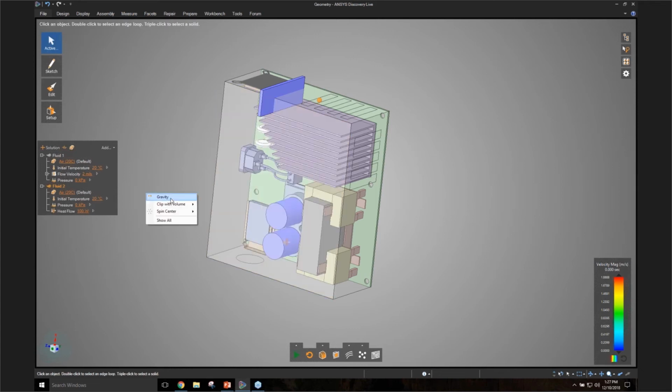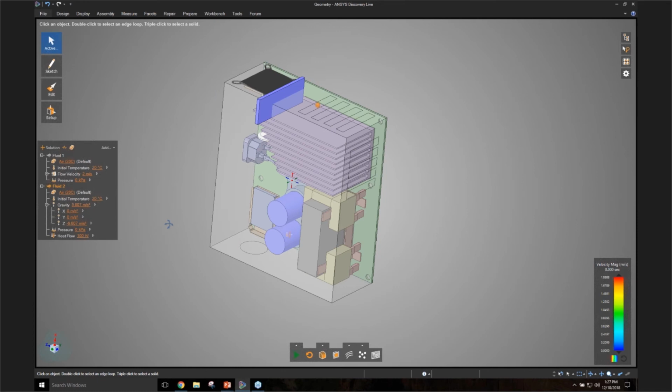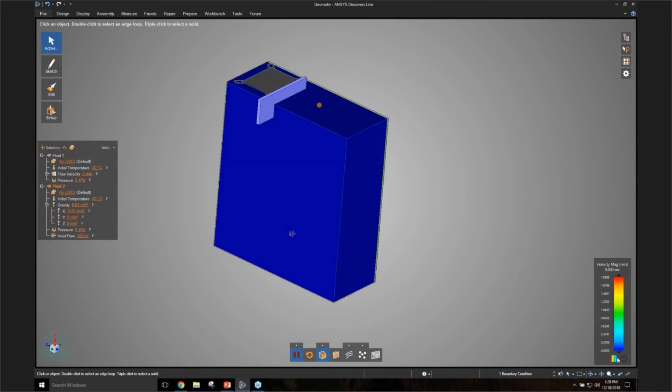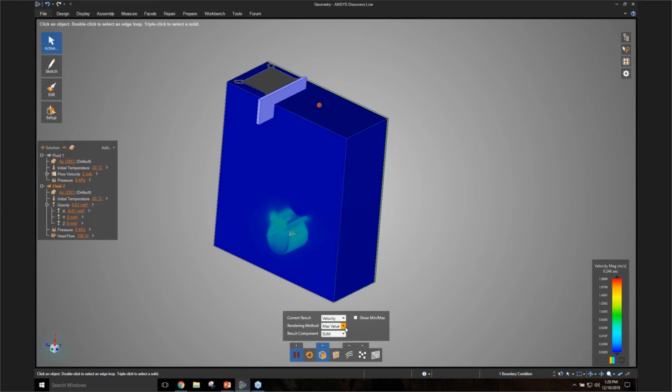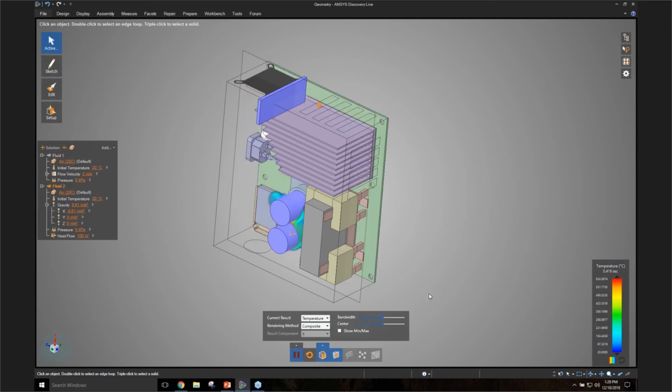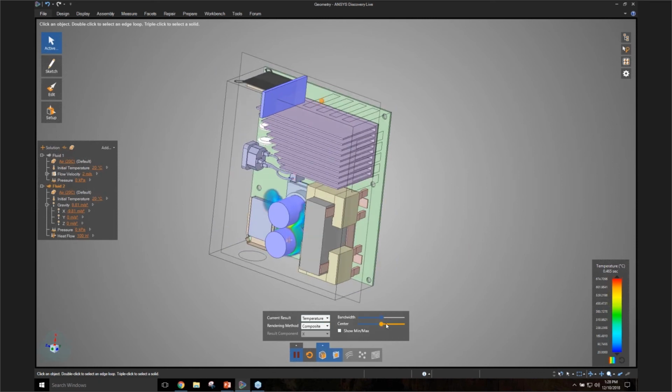Now all I need to do is specify the direction of gravity. Okay, and let me make sure it's in the right direction. So it should be in the negative x direction. You can look on the bottom left, x is in the right direction. So minus 9.81 and then 0 over here, and then just click play, right? So as soon as I do that, let me turn this on. You can see the temperature plume starting to develop, right? Here we are.